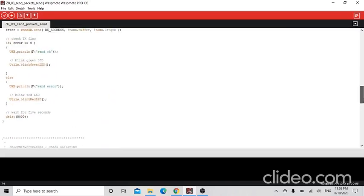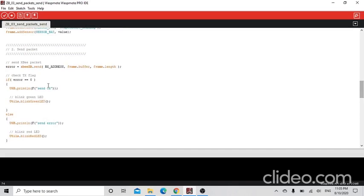So here is the send on other Zigbee. We can use the Zigbee function dot send function of the Zigbee class. So here we need an address, frame buffer, and frame length. If there is a send OK, it means the frame is sent successfully, and if there is an error in sending the frame, then it will show send error. I will show you the output of this program and the sender's program and the receiver's program in the coming slides.